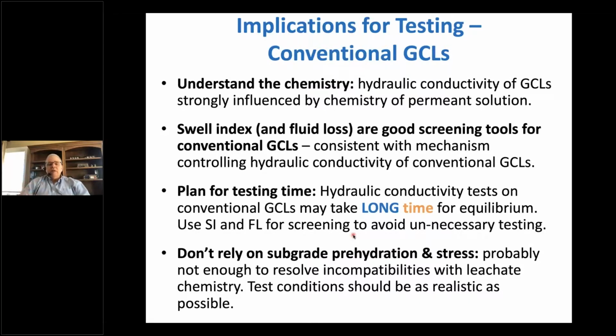Plan for testing times. Testing times can be long. I showed things on the order of years. That's not that common. Maybe that's a little bit dramatic for a webinar, but it won't be done in a week or 2 weeks. Well, unless it's very permeable. It's going to take 3 months, 6 months, sometimes longer. Be prepared for that. Plan ahead and use screening tools if you can, like swell index, to avoid unnecessary testing.